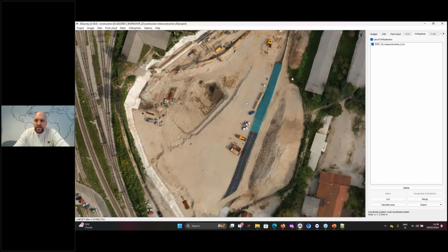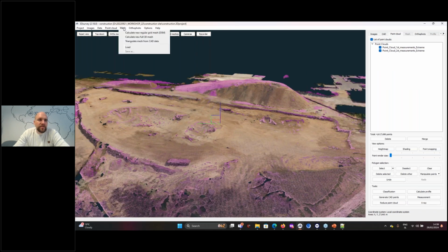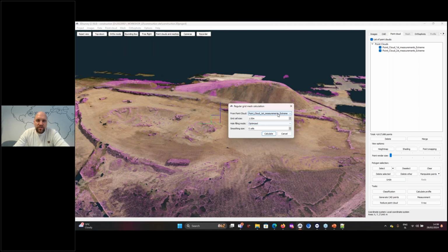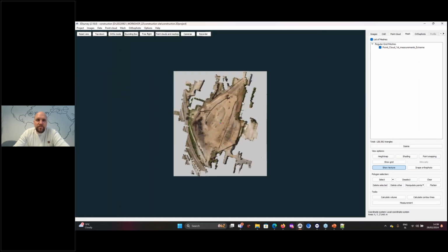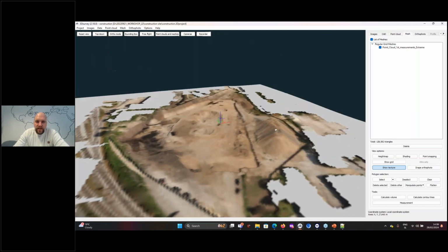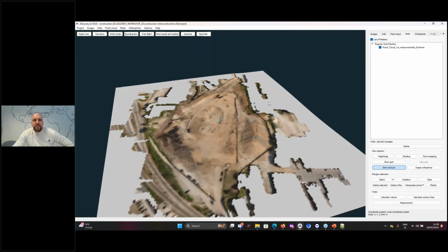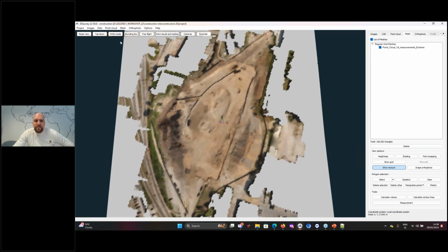And this is what the area looks like. Right. So these point clouds already contain only ground points. So here all we need to do is just create 2 digital terrain models. Let me set this one to all. So setting the extrapolation to all means that we also get the area around here, which is white. So this is extrapolation. It's not very accurate, but at least we have some elevation there. And DTM for the second measurement.